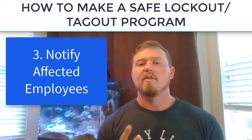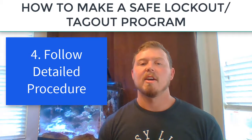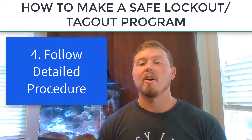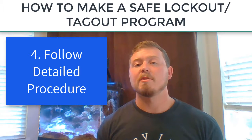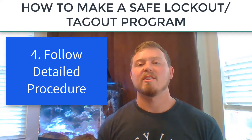Step 4. Follow the detailed procedure. The employees completing the procedure must understand it and be able to follow it exactly in order to prevent potential injuries or damage. As part of this step, the employee must also verify the lockout by attempting to start it or some other method. Once the step has been verified, they must attach a lockout or tagout device to the machine to be sure no one will attempt to start the machine while it is being worked on.